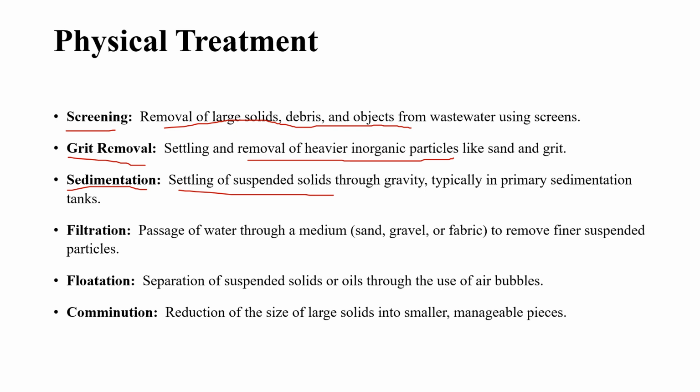Usually, it is not recommended in the physical treatment. The fourth one is the filtration process. Filtration is nothing but the passage of water through a medium. The fifth one is the flotation process. Flotation is the separation of suspended solids using air bubbles. And the sixth one is the comminution process, the reduction of the size of large solids into smaller manageable pieces.